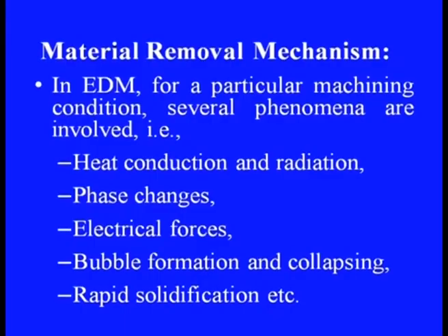Now, let us look at the material removal mechanism involved in the EDM process. In EDM, for a particular machining condition, several phenomena are involved. These include heat conduction and radiation, phase changes, electrical forces, bubble formation and collapsing, rapid solidification, etc. The thermoelectric phenomenon is the most appropriate theory for the explanation of the electrical discharge machining process.